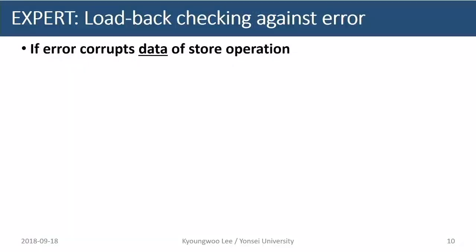What about the store case? We need to think about two cases. One is data corruption. The other one is address corruption. Our main idea is load-back checking against errors. Sorry about that. The main idea is that rather than checking before the store operation, we check the updated one after the store operation.